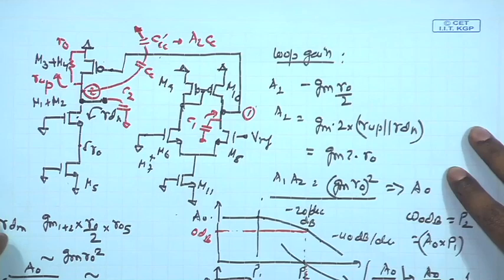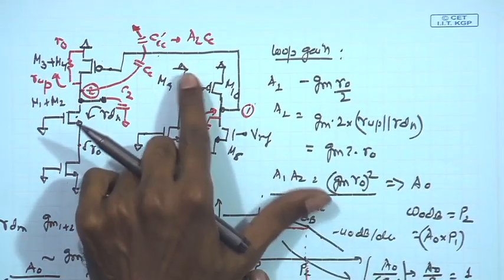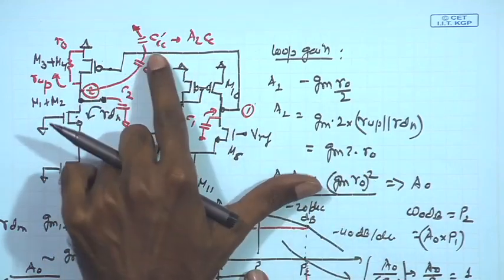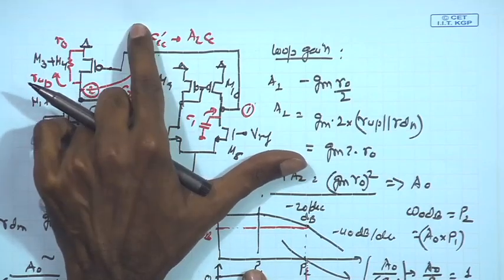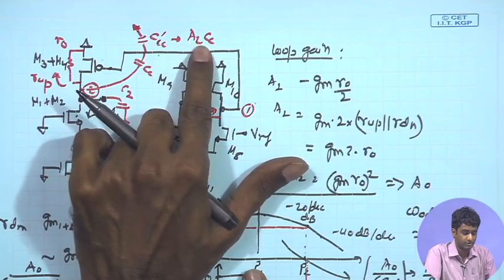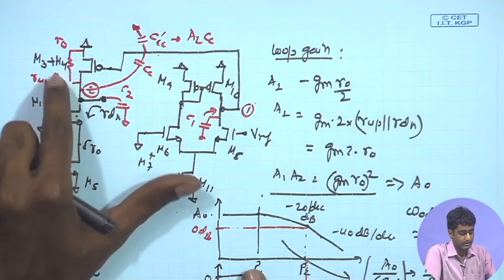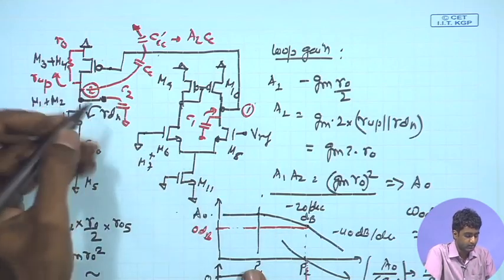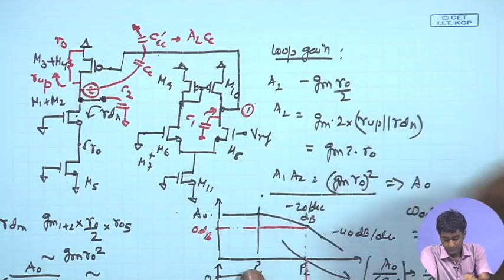Welcome back. So, let us resume our discussion with which we started. Here we looked at the composition of the common mode feedback loop, where we tried to put a compensation capacitor between node 1 and node 2, and that resulted in a larger equivalent capacitance between this point and AC ground by a multiplication factor A2, which is the gain of this particular stage. And in that case, the additional capacitance contributed at this point, coming because of the CC dash, will be close to CC.